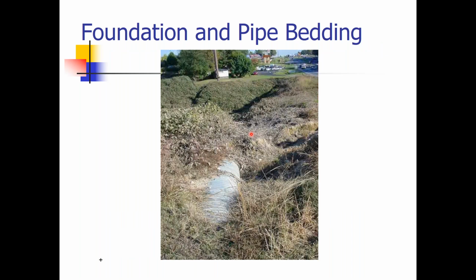Here's a pipe that was put down. I'm not going to sign off on its foundation and the pipe bedding. You can see the pipe is exposed. It's not covered very well. There is some vegetation over it, so we need to come in and clean that up so that we keep that well.